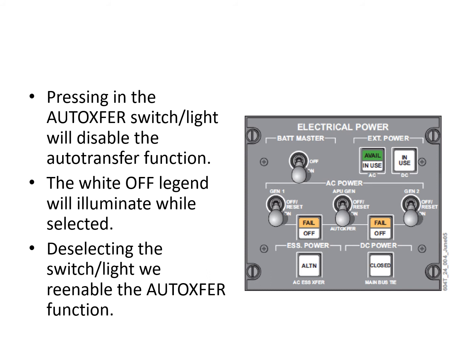You never really want to switch off the AC essential power, so there's no off position. It will either automatically transfer to the alternate source, or you can force it to transfer to an alternate source. The DC power, this is just the single DC power switch. You'll notice there's no switches for the TRUs, by the way. None at all. They just come online when they're powered from the AC bus. You can't turn them off.